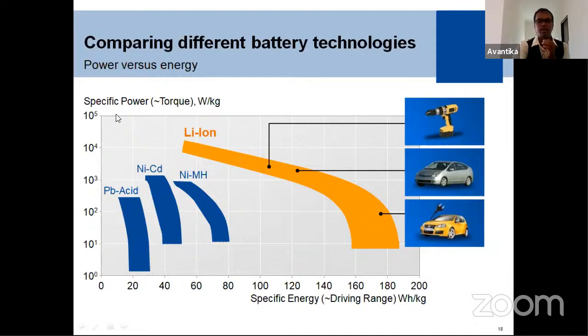So this is the graph between specific power and specific energy. In every device, the specific energy and the power are both important. I will tell you the difference between energy and power. Lithium ion batteries are also energy devices. On the other hand, the supercapacitor is also one of the energy devices. The difference is that the supercapacitor has more power but less energy.